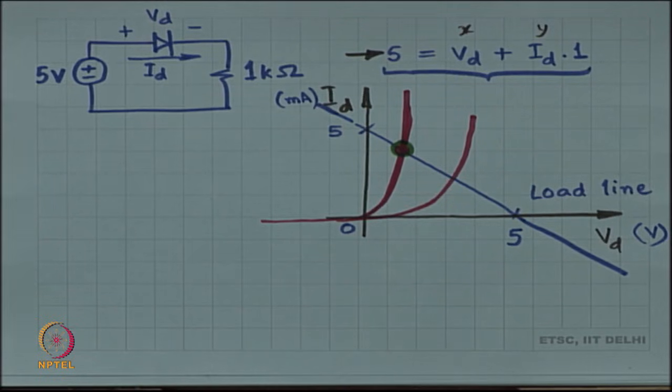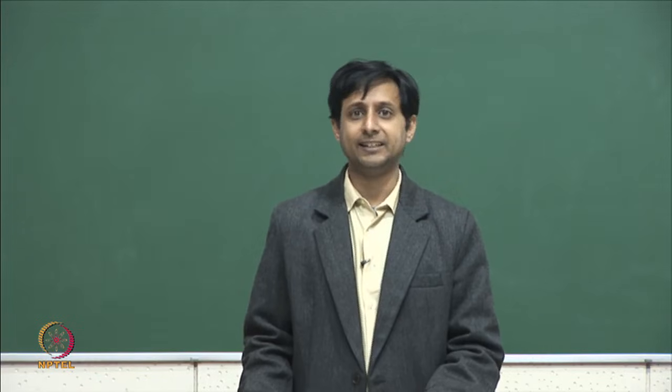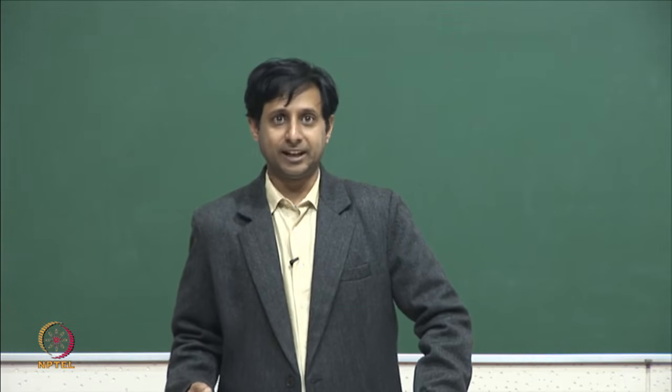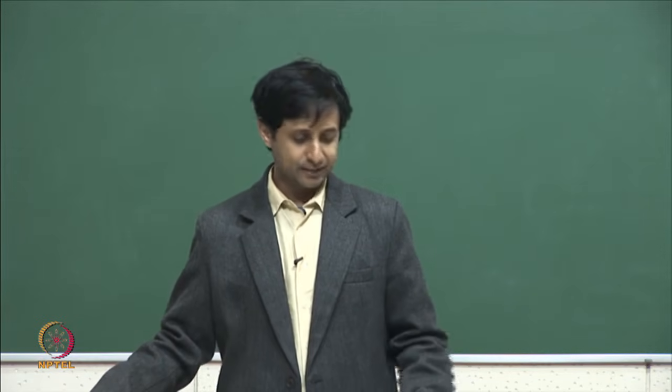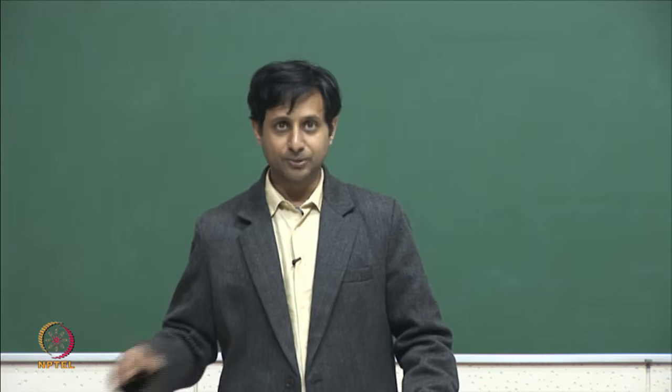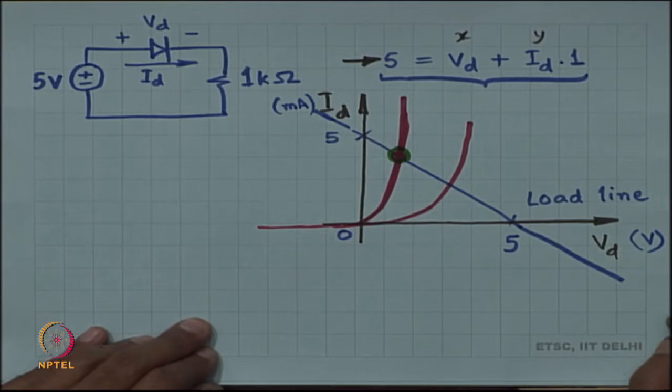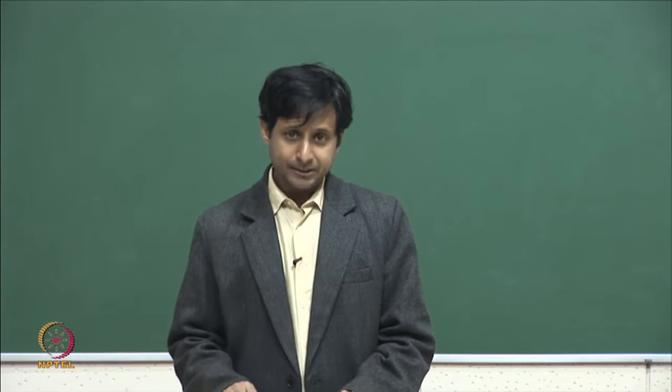So, this is called the load line technique, and one of the big reasons why we are studying diodes at all is to understand this load line technique, because the load line technique is going to appear in all kinds of places everywhere. I mean, without any warning I am going to start drawing a load line, and then you have to recall what you studied in this diode lecture. Okay. So, is this load line technique understood? All right.